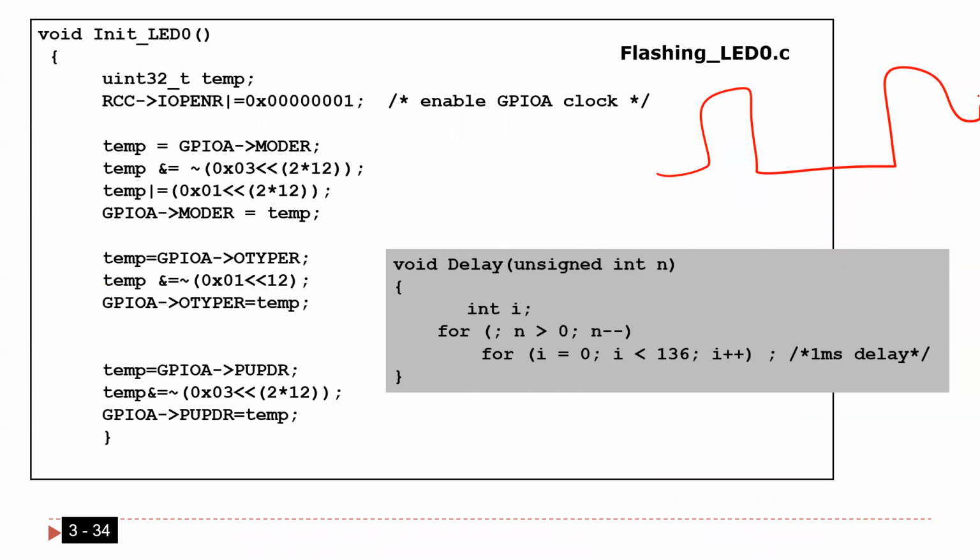And as I told you in the last lab, the time was too long. 1 second is too long for sure. 1 second, or 2 seconds, or 4 seconds. All these numbers are too long, but still you can use the same lab. You can use small numbers like 1 millisecond, 2 milliseconds. However, I didn't ask you to do that in the last lab because we don't have a scope. If you set 1 millisecond, you will see the LED on all the time. Is that okay? If you have a scope, you can still use the same program and generate small signals or short times.